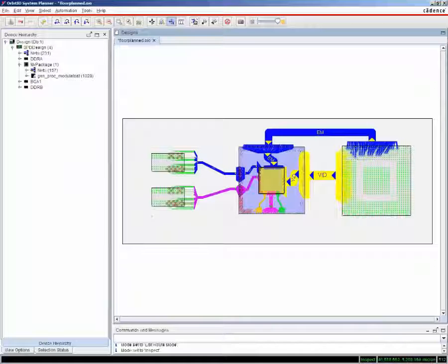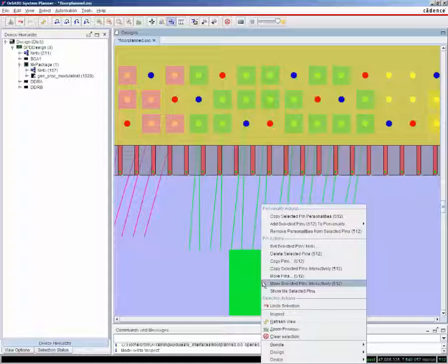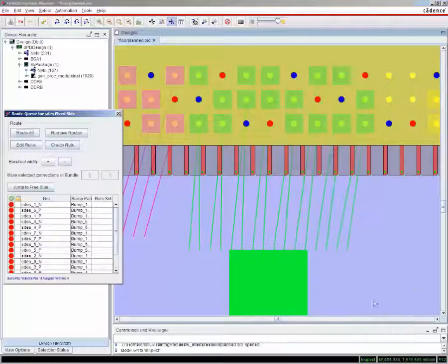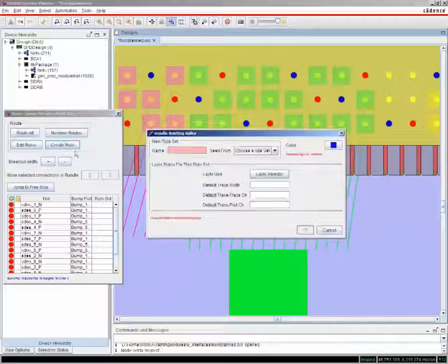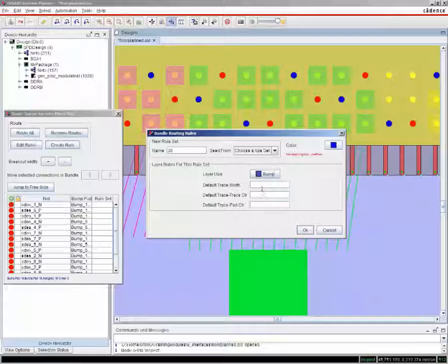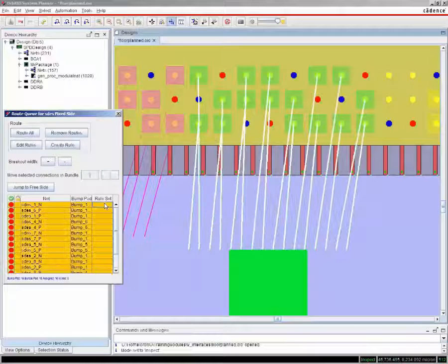I will now show breakout route feasibility that may be used to manage the ordering of pins. I specify the layer it will be routed on and define a 30 micron width and spacing rule. I apply the rule to each of the pins, and please note that I can specify multiple rules and apply them to different pins in the bundle.